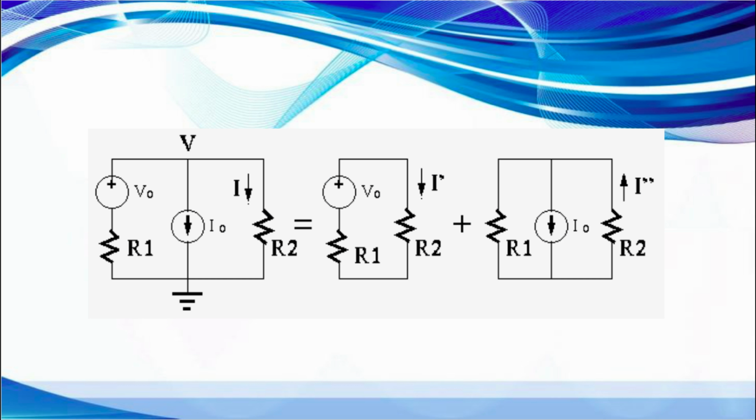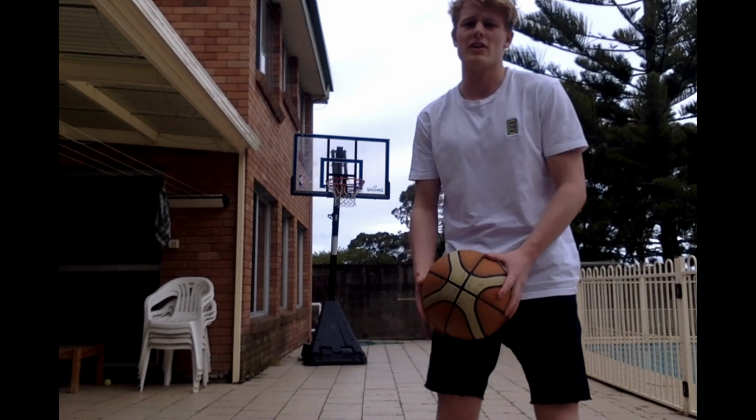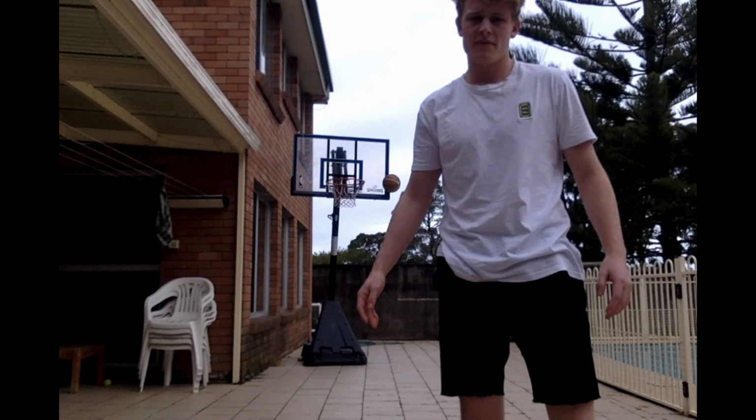Similarly, in electric circuits, the superposition theorem says the current through or voltage across any element of a network is equal to the algebraic sum of the currents or voltages produced independently by each source. When used effectively, the superposition theorem can make solving complex electrical circuits a breeze.